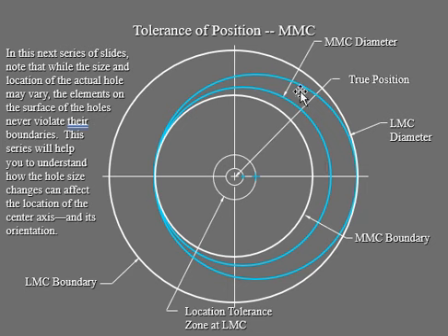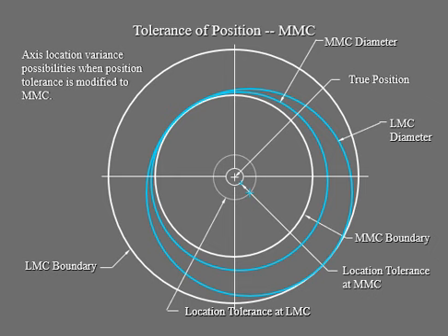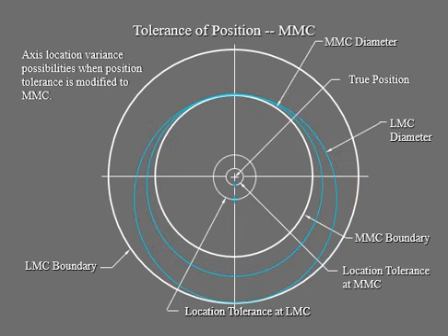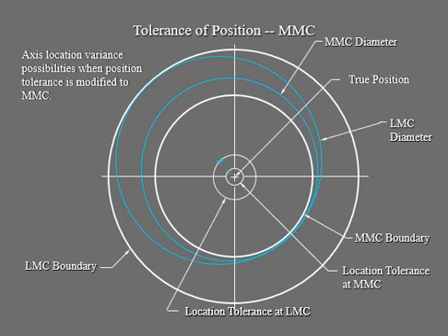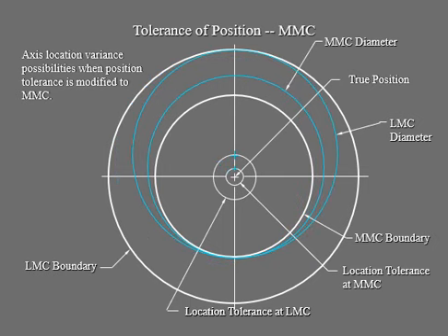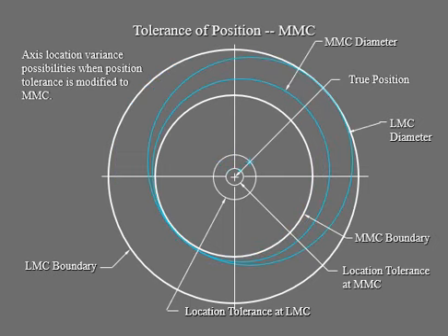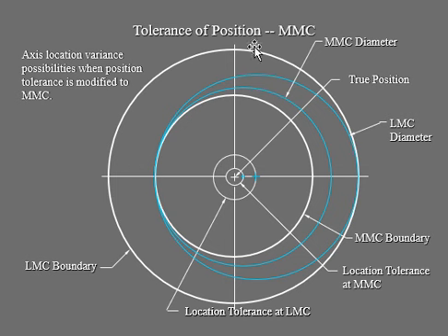These are all of your diameters in the blue drawings right there. So the blue lines or blue circles are going to move around. These are what the variations are about. When you manufacture the part, the hole can be there, it can be here, in different parts it can be there, but of course still in our tolerance zone, even with the MMC material in it. So now the actual position of that hole can be anywhere like that.